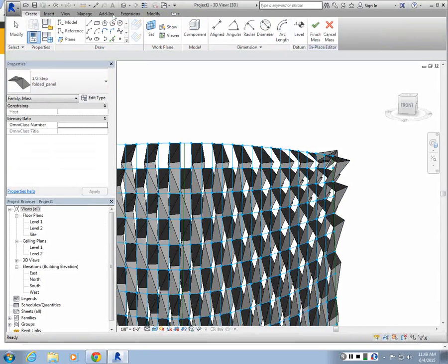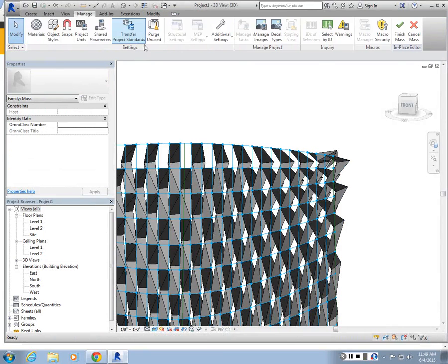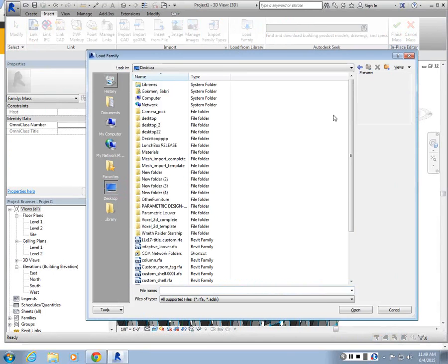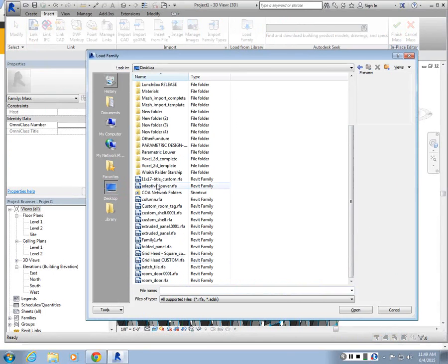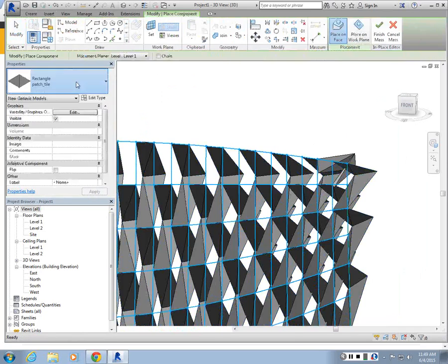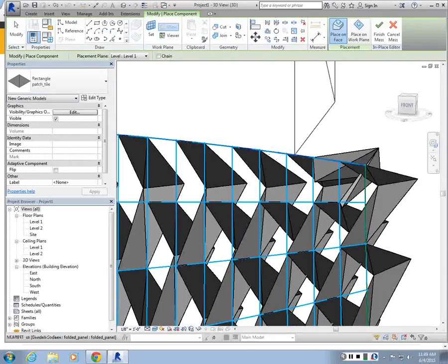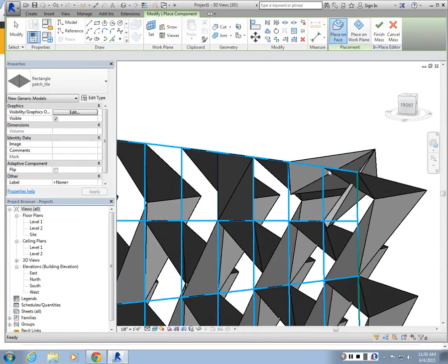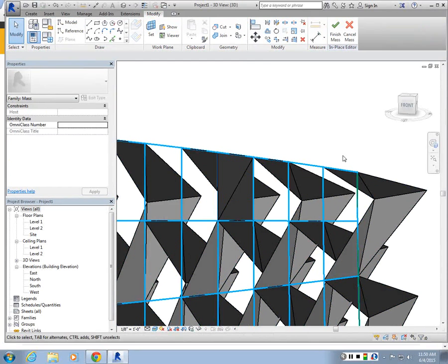If it's not here, we could load it. Load family. Desktop. Patch tile. And I should be able to place it here. And this guy I'm going to delete.